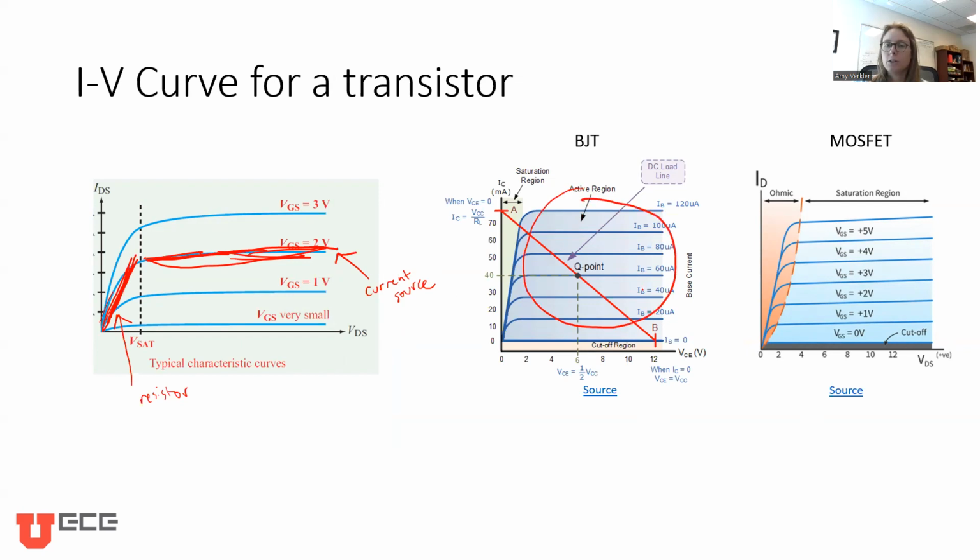And you can see the different curves represent the input current. So as the input current increases, the output current increases. And notice that I'm inputting like 20 microamps here and getting out something like 15 milliamps. So I'm multiplying by somewhere between like 100 and 1,000